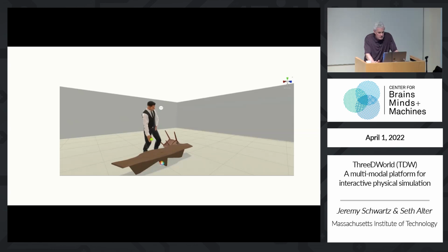In the reach sequence, the ball target object is being randomly positioned, and its location left or right of the agent's centroid determines which arm is used to reach with. So we plan to improve on this by layering IK on top of motion captured reach actions to improve the realism and fluidity of the resultant motion while allowing dynamic adjustments of the reach target position.